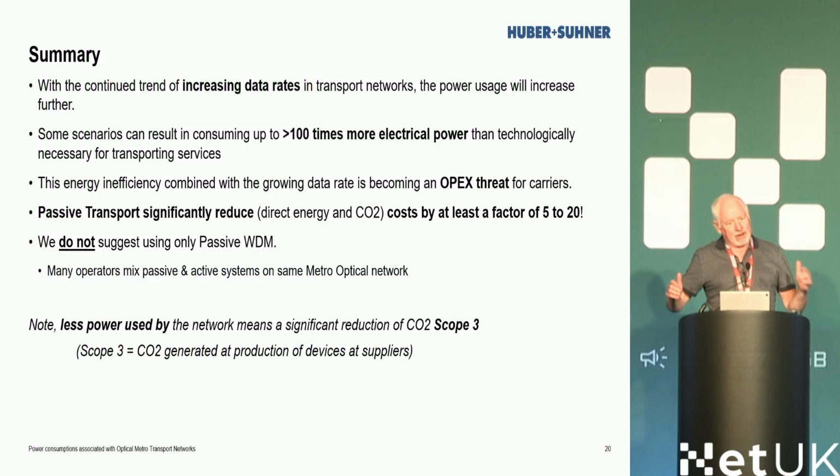If you were using passive WDM demuxes in your network, make sure that the passband within those 100 gigahertz spaced DWDM systems are greater than 75 gigahertz passband, because some of the modulation techniques used on some of the 400 gig and beyond transceivers will create errors if you try running that through a standard 50 gigahertz passband interface.